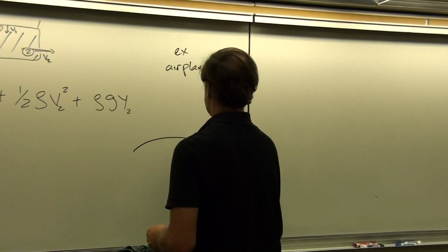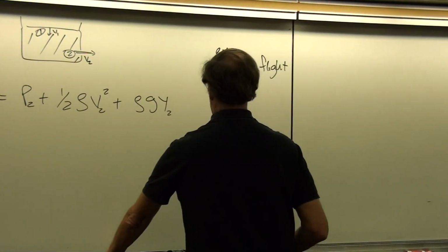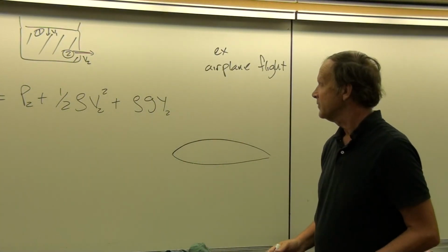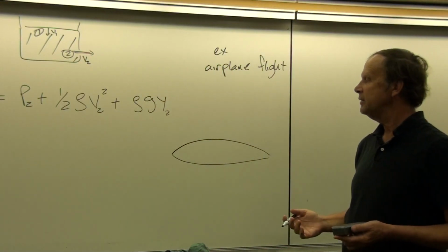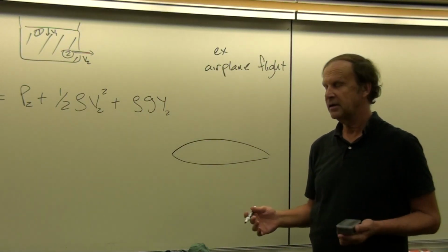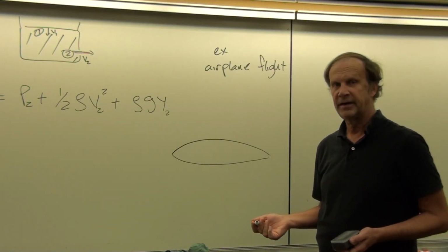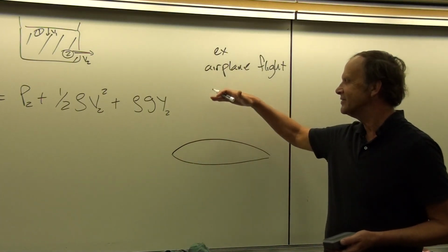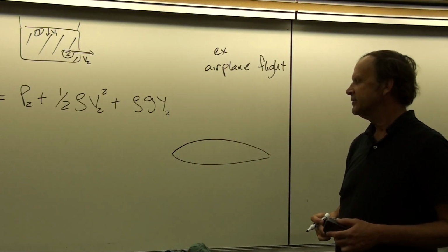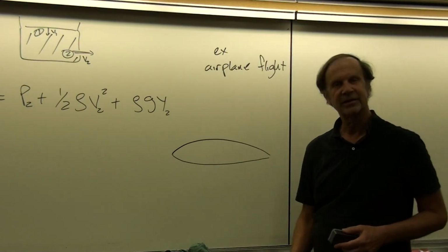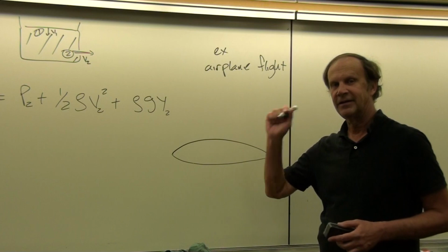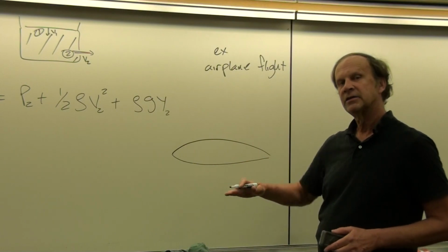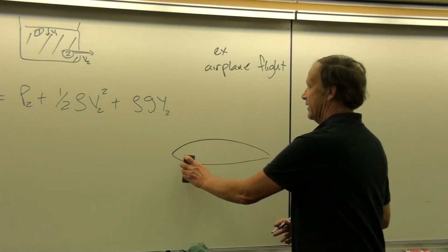So in airplane flight then, let's not worry too much about the angle of attack. Now if the upper curvature and the lower curvature are the same, there actually are wings that are made like this, but they're basically just stunt planes. Because in a stunt plane, a lot of times you need to fly upside down. And so if you fly upside down, then having the wing curved to enhance upward motion is going to also work against you, and it's going to tend to make you want to crash into the ground because it'll tend to make you want to drop. And so they just use the angle of attack to change the streamlines in a stunt plane.